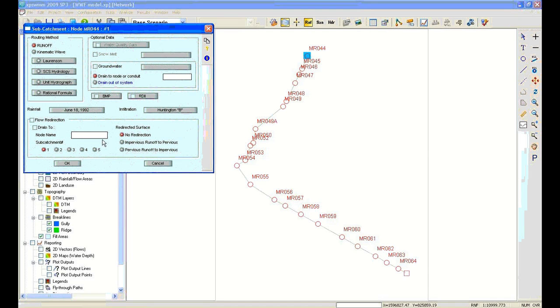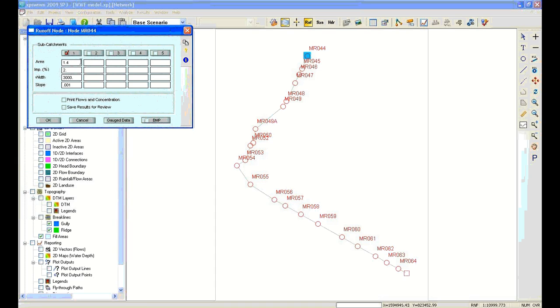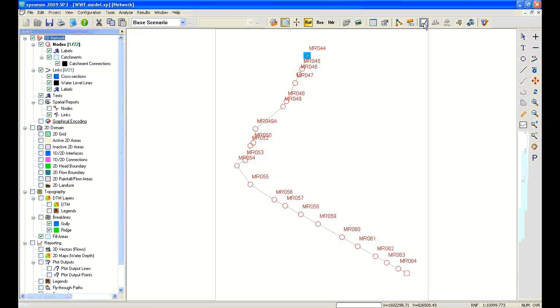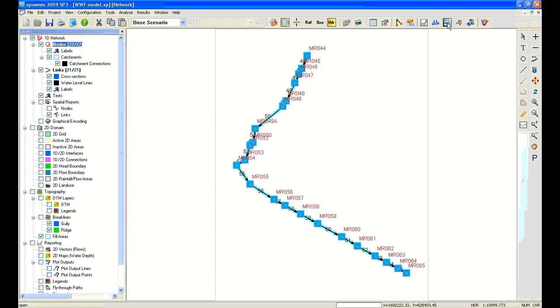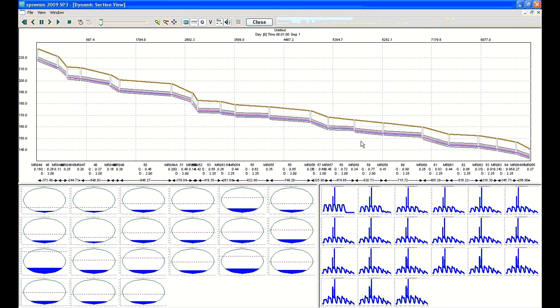Now in this one, notice that I didn't use 2 areas. I just used 1. I have just an area that encompasses the entire drainage area. And if I look at this in a long section, once again, we can see that we had some flows, but the flow that was about half full now is almost full, this pipe right here, but we didn't get any surcharging going on. So in terms of modeling, we're probably in pretty good shape for this model.